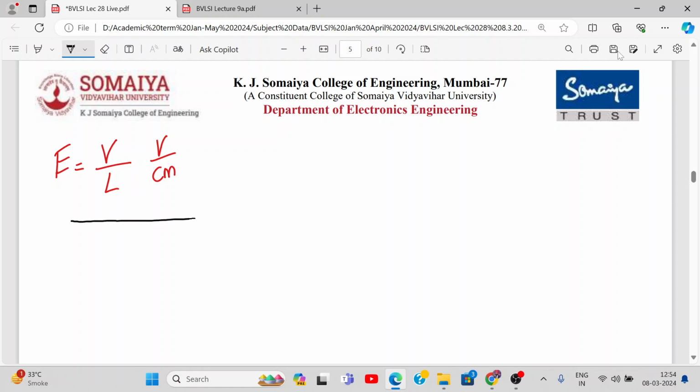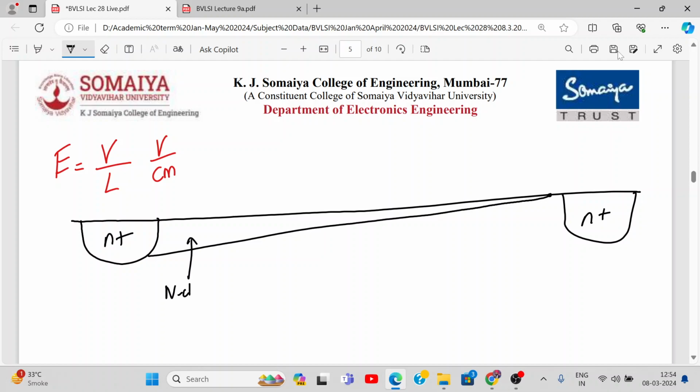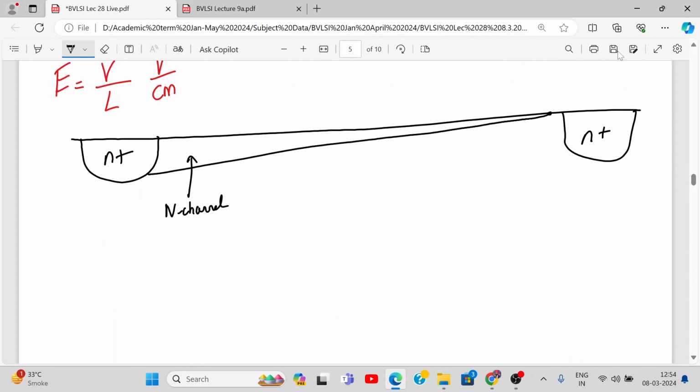Now electrons. Now see, listen. This is very dicey. You can lose the track over here. Listen very carefully. So this is source. This is drain, and as I told you, this is very near towards the drain end. Drain end से it's away, but it's very much nearby also. यहाँ पे, somewhere around here. Okay, so this is my N channel. Okay, this is the situation. And my depletion layer has increased to a tremendously high value.